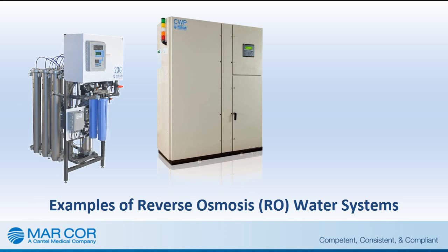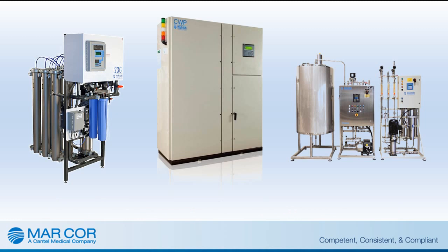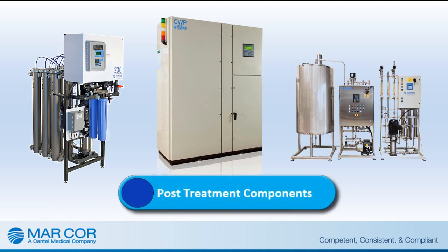After the pretreatment, the water will enter the RO, where a portion of the water will pass through the RO membrane and become purified product water. After the product water leaves the RO, it must be distributed to the various points of use. This water has been highly purified at this point, and various post-treatment components are needed to keep the water in as pure a state as possible. The variety of post-treatment components will depend on the type of distribution system that is being used.